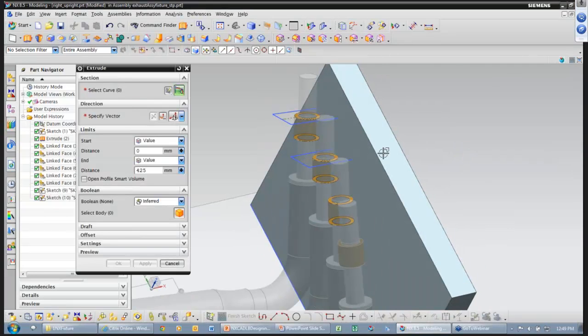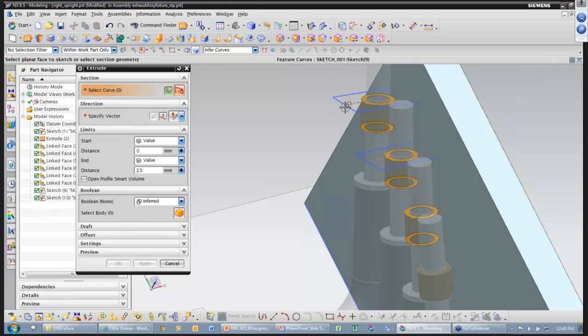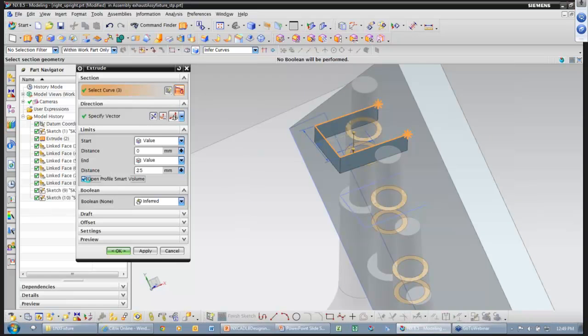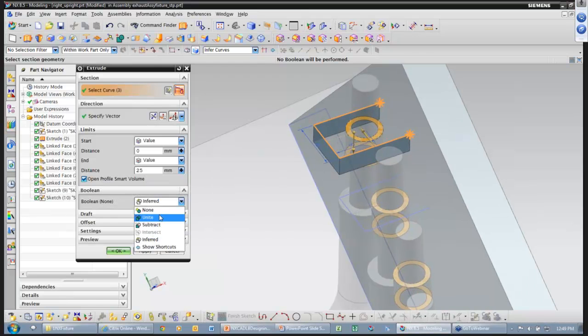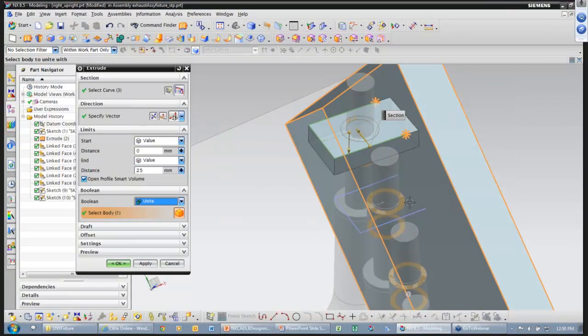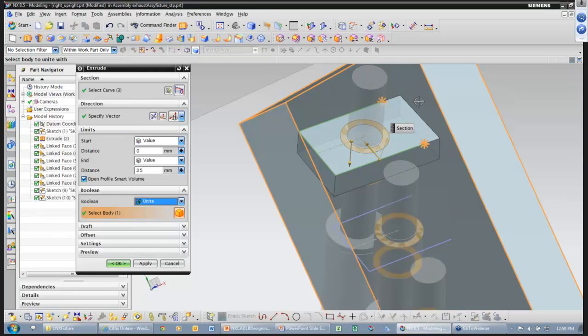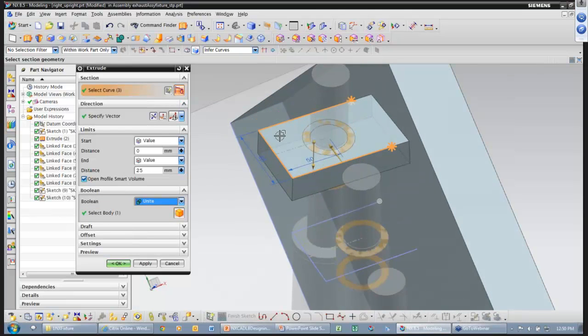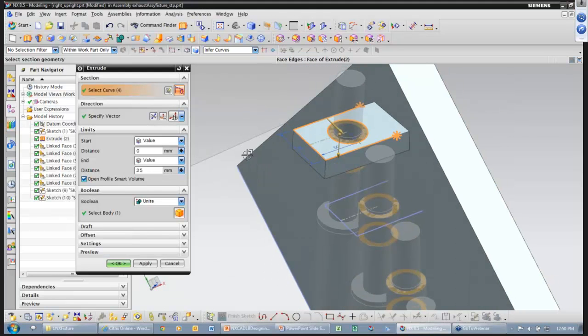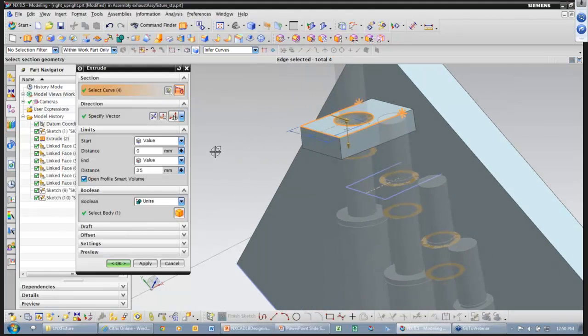So I'm just going to come up to extrude. Go ahead and grab my profile. Now it's an open profile, so it's wanting to do a sheet body. But if I turn on that option in 8.5 that we covered earlier a couple months ago in the Lunch Bytes, I can come in here and say I want to Boolean that and I want to Boolean it to that solid. So notice how it extends over and Boolean unites up to that first feature, that vertical extrude. While I'm in here, because I have the edge of that copied, why not select that edge so it keeps a void as it extrudes. So there I have the basic profile.